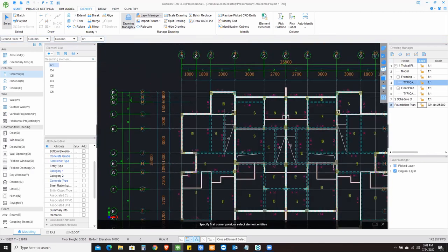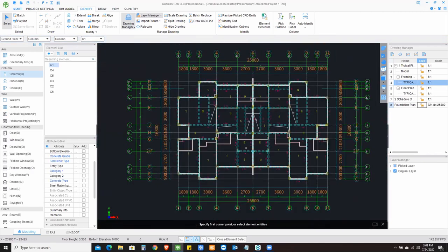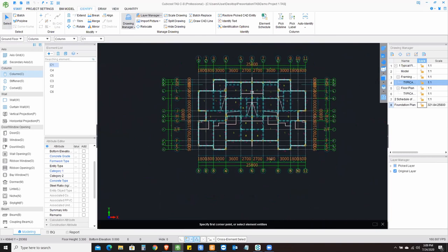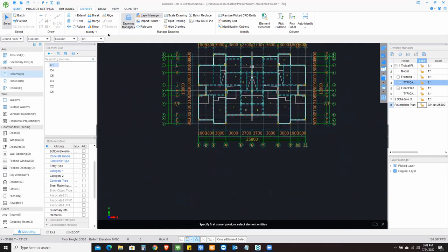And this is really useful when you have got multiple towers standing face to face. Obviously in the master plan, it shows you the face-to-face thing. But then in separate drawings, you are still stuck with rotating the drawing. So what you can do is use these 2D functions and rotate the 2D drawing and make it face-to-face or whatever angle that you would like based on your project.